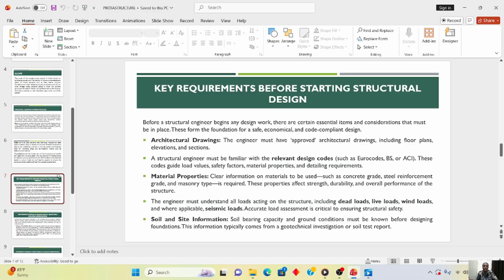There are sites that could have varying soil bearing capacities, and then when you generalize it, at the end of the day, you see that settlement begins to occur, and at a degree that was not expected, all because proper soil tests were not conducted. So that is just another item.